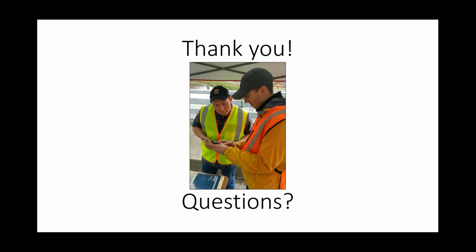That's a good question. The bridge, it's mostly a practical consideration. It's relatively lightly trafficked, has these big sidewalks, so we can access it easily. When we did go out to do the forced vibration, we got a lane closure so that we could operate towards the middle of the deck. That allowed us to test with both ambient traffic and with our forcing system. So that meant that we could get some pretty good results.